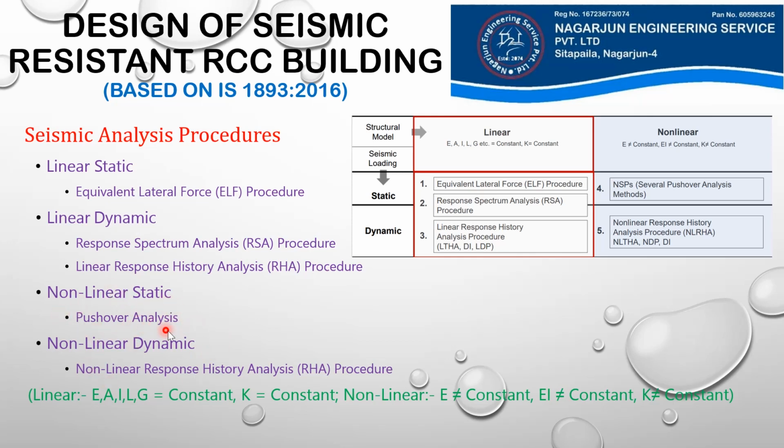Pushover analysis is mainly used, after performing this equivalent lateral force analysis, we can perform the response spectrum analysis also. But pushover analysis is mainly used to ascertain the strength of an existing structure, not for the design of a new structure, but for determination of the strength of a currently existing structure.